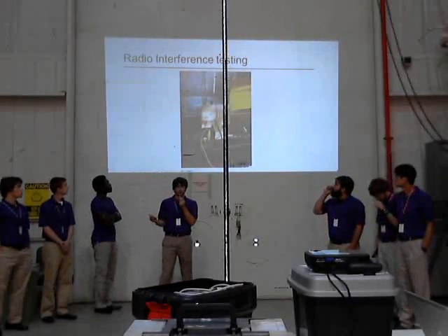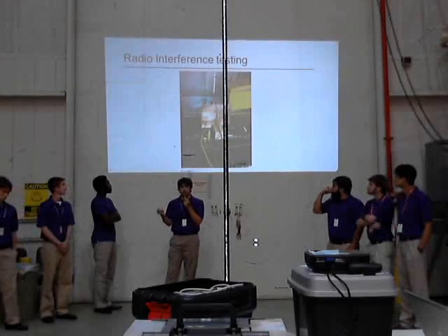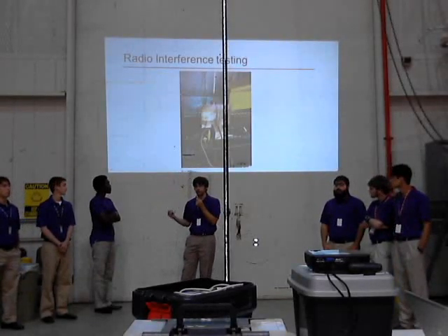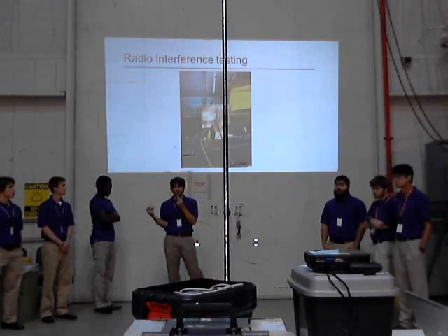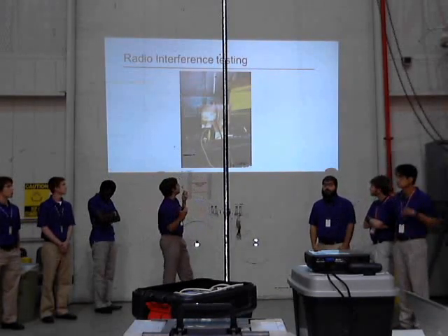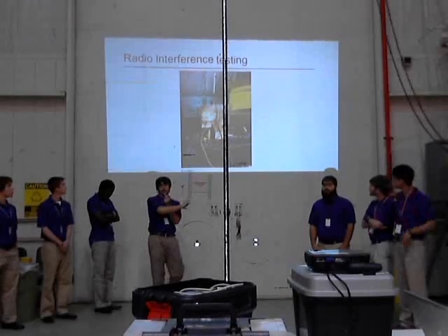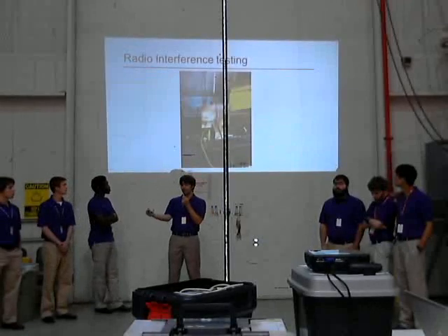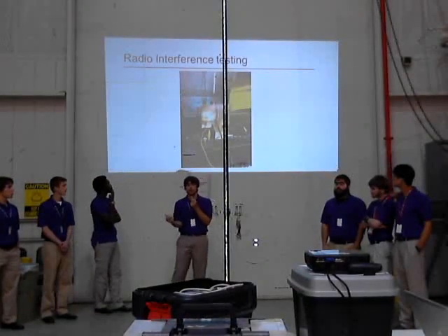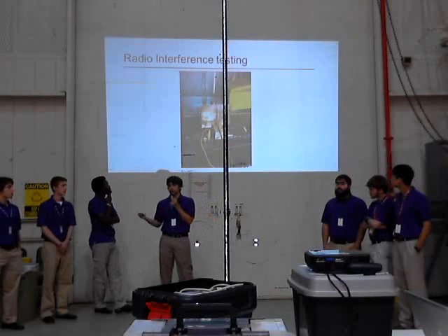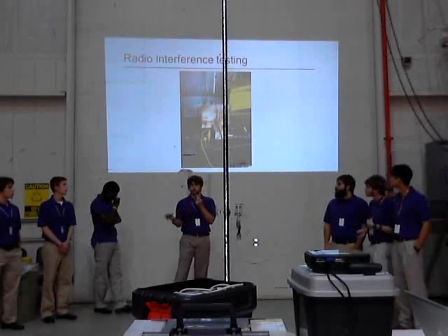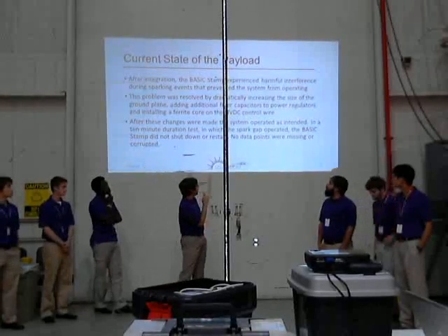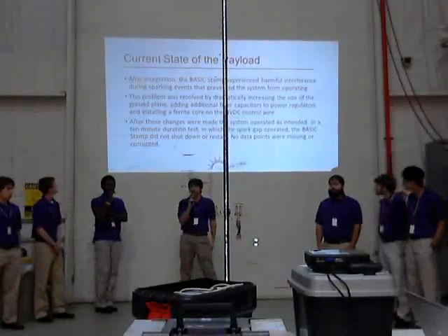We also had a concern that the sparking emits a lot of radio noise interference, and we were concerned that that spark could affect the radio locator beacons or the cut-down mechanism for the balloon. So we put a spark gap in a chamber. We ran it for 10 full minutes of constant arcing right next to the beacon and the cut-down mechanism, and neither the beacon nor the cut-down mechanism were interfered with, so we're fairly confident that we'll be fine for flight.